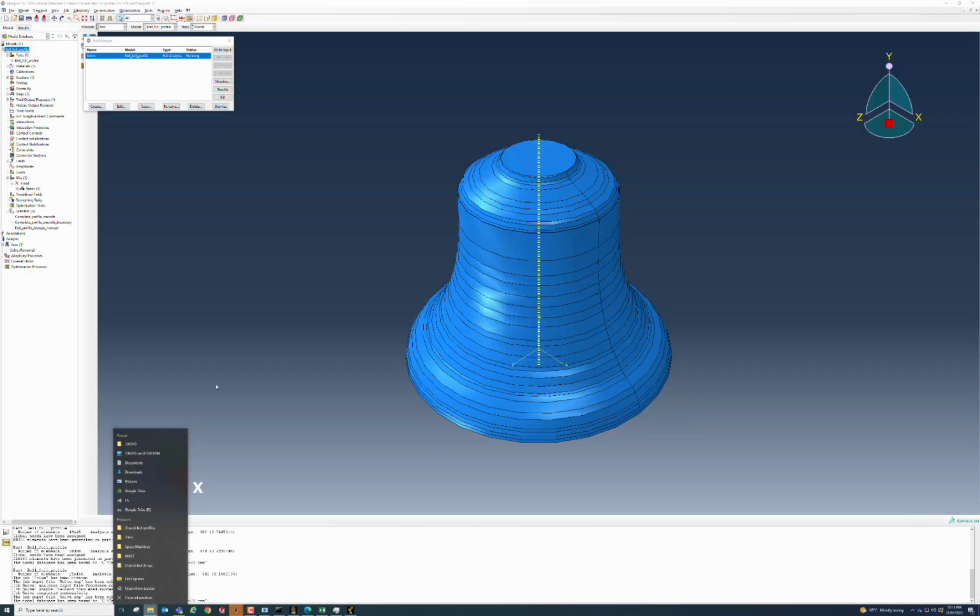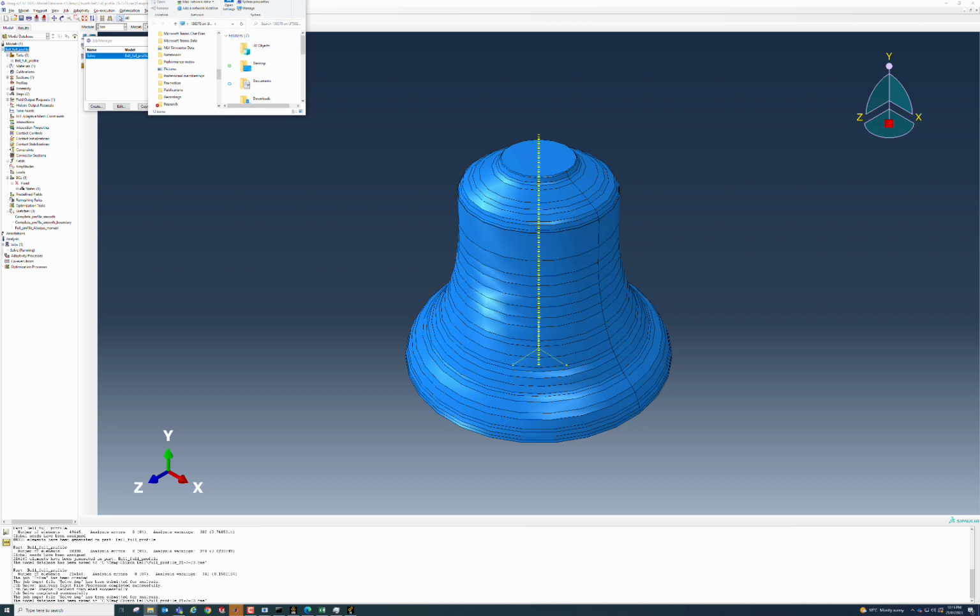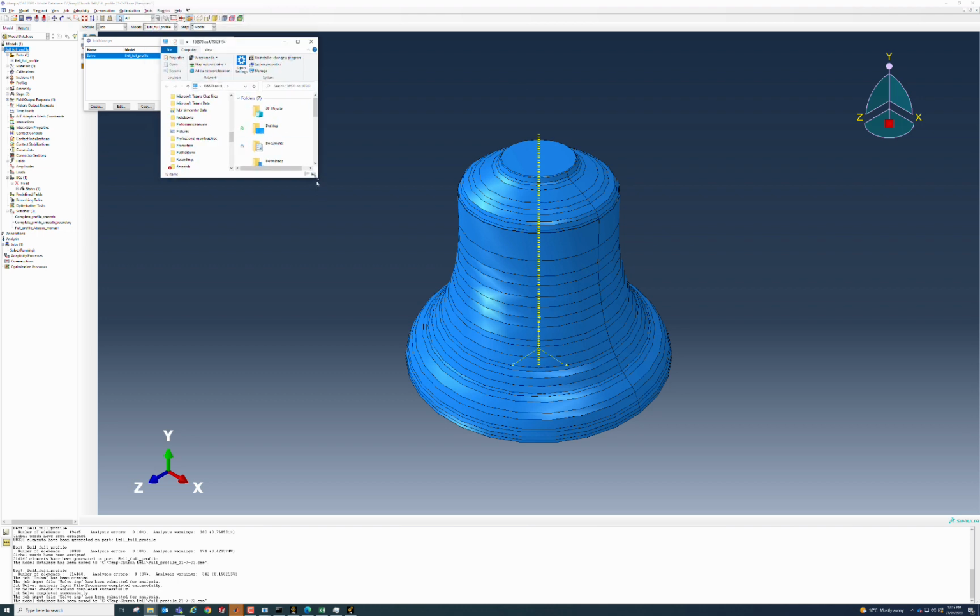Now when the job's running on the solver, I can still go in and make new model files. I can still use Abaqus CAE, the graphical user interface, in the background essentially, or indeed in the foreground. Leave the solution running in the background. So now I'm going to go in and create a duplicate model file from the one that we've created, and make some changes to that.